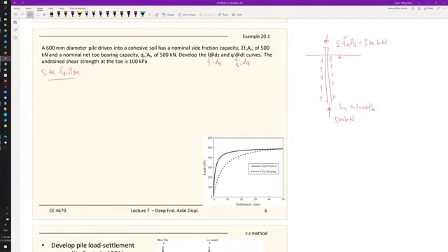We know that the formulas that we have previously involve a Ks term. So Ks equals Ms times the diameter of the foundation, and then times the total friction. And if we plug in the numbers, Ms for this case of clay soils and piles is 0.004. You can reference the previous slide for the table. And then the diameter is 0.6 meter, and the total friction force is 500 kilonewtons.